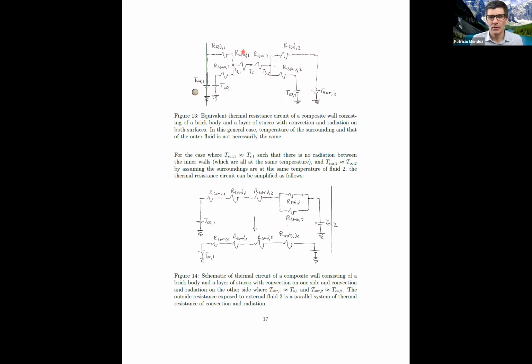What you would do is follow these steps one by one and say, okay, step one was find the parallel resistors, like here. These parallel resistors, turn them into an equivalent resistor, that is this case here. Step number two, find all the series resistors. Boom. I sum all of these, and we're good.